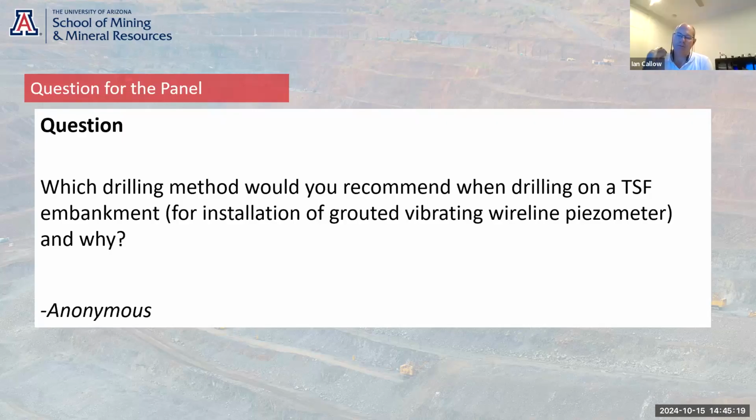I mean, the other thing is with your drilling methods, you need to make sure you've got control of your hole. If you're drilling into a foundation that's got some pressure on it over rock fill, you won't actually see that you've drilled into a pressurized foundation. You'll lose it at the transition under your confining layer. So you really need to be sure when you drill in, you are doing your full risk assessment.